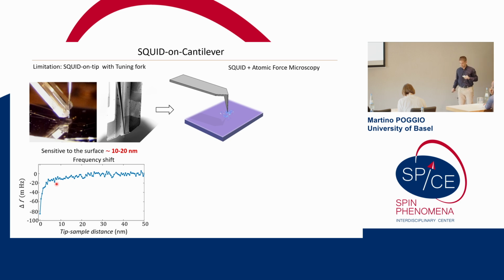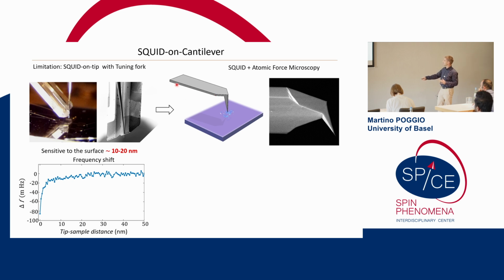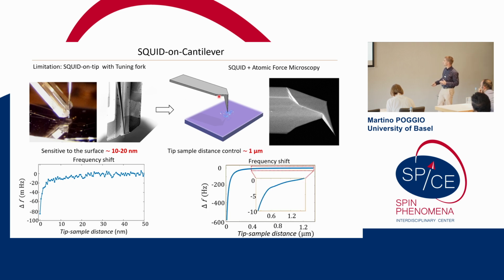So in our lab, we spent quite some time trying to improve this, and we developed what's called a SQUID on cantilever. So the idea was to take an AFM cantilever, which is designed to solve exactly this problem. So it's a compliant mechanical object that when you bring close to a sample, provides a large frequency shift even when you're quite far away. Okay, so you can see here the scale. Now we're talking about a micron, and we're talking about frequency shifts of hundreds of hertz instead of tens of millihertz. Okay, so then the idea is you can just hook this up to your commercial atomic force microscopy setup, and it just controls the distance, and you never have to worry about crashing.